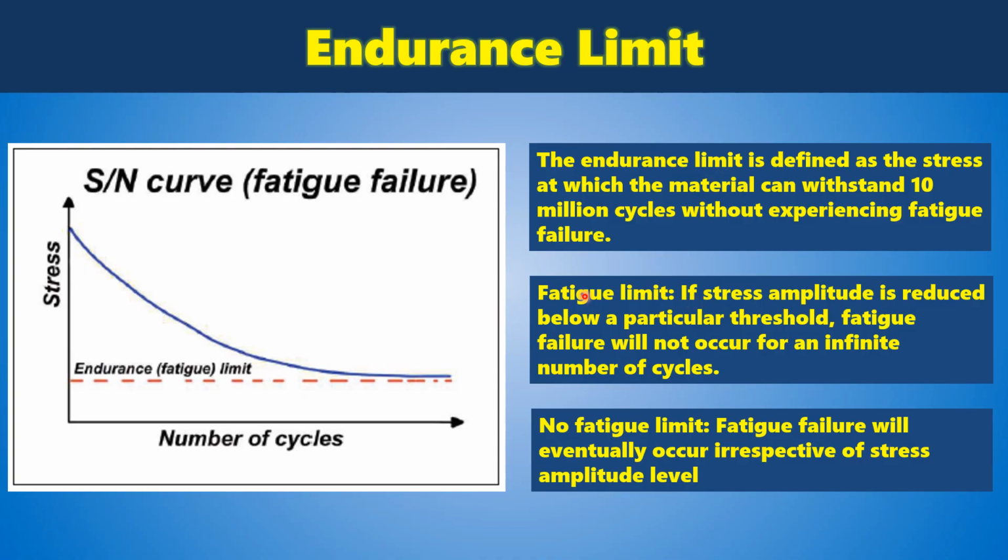Now, the fatigue limit. If the stress amplitude is reduced below a particular threshold, which means if the material sustains a stress that is lower than the endurance limit, fatigue failure will not occur for an infinite number of cycles. Theoretically speaking, if the material sustains a stress below the endurance limit, it can withstand an infinite number of cycles.